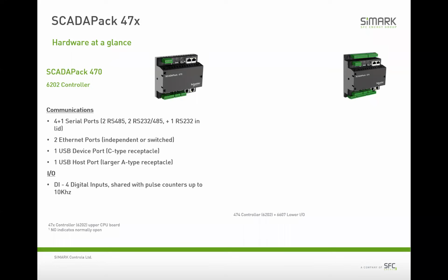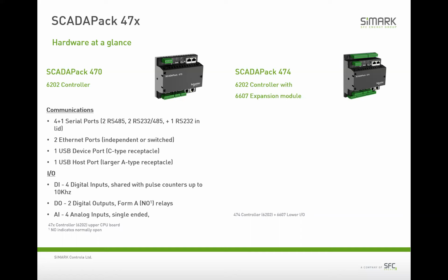So we have 4 digital inputs with pulse counters up to 10 kilohertz. So more pulse counting capability there. 2 digital outputs and 4 analog inputs on the 470 controller board. Take that controller board, add in a 6607 expansion module underneath there, and you've got the 474. So that's the expansion module all packaged in there, ready to go.